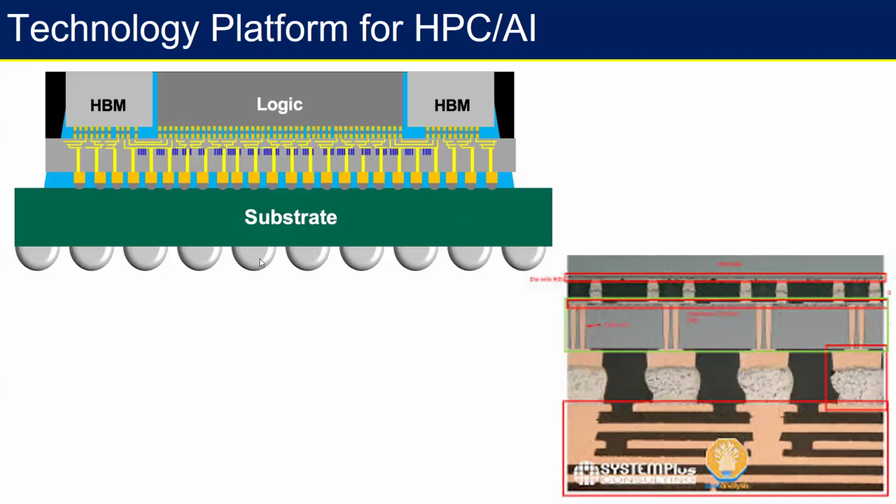Okay, so that's how you see it, and the material choice could be very different. So here I am using SAC material. Here for micro bumps, I could use just copper pillars, with some finishing materials like titanium, right? So the choice of material depends on at what abstraction level and what the purpose of that particular contact or material is. It's like, if I'm going from the house, I may need a very small road, and that road could be made of concrete, or it could be made of, let's say, just dust, or sand. So that depends on what you require from that road, right?